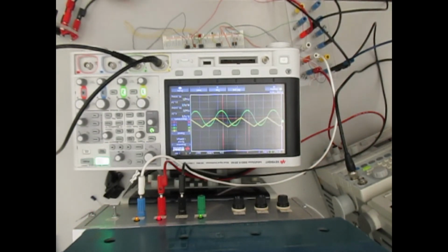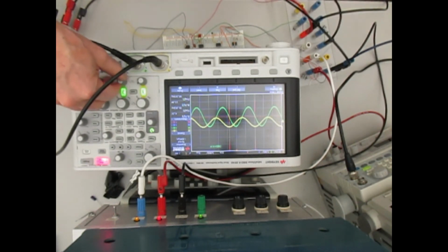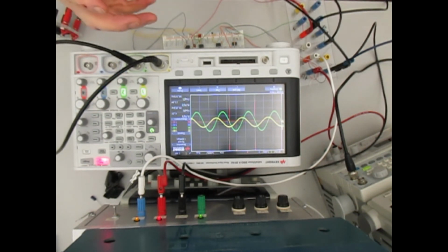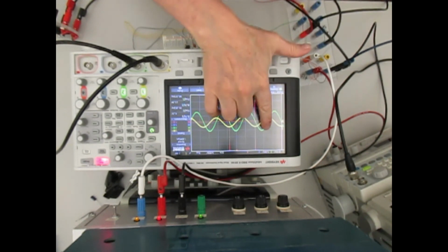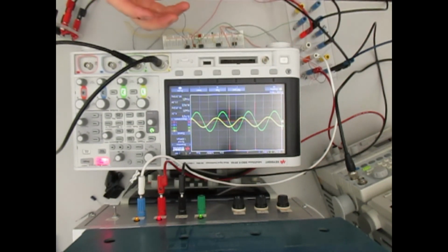Okay, and then we'll go to our sine wave. Here, I'll stop this. Okay, and again, this should be minus cosine, but because it's an inverting amplifier, at the zero cross it starts at the positive and comes back, so it's actually showing cosine. But again, that's because we have an inverting circuit.